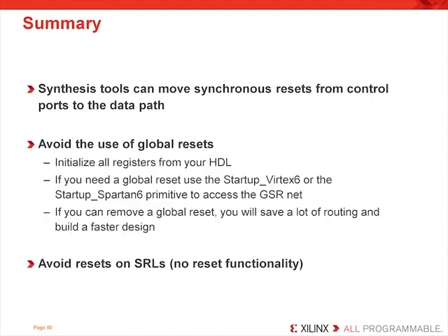Continuing on with our summary, synthesis tools can move synchronous resets from control ports to the data path, and that's a good flexibility and a good reason to use synchronous reset coding rather than asynchronous reset coding. This allows you to reduce the number of control signals you might have, which allows the synthesis tool to minimize the control sets and allow different pieces of logic to be placed together in the same slice or into the same CLB.